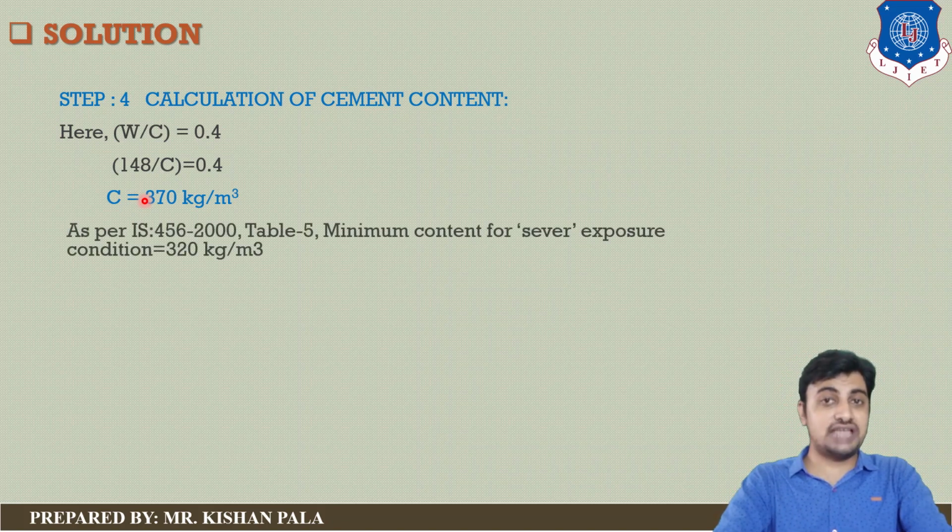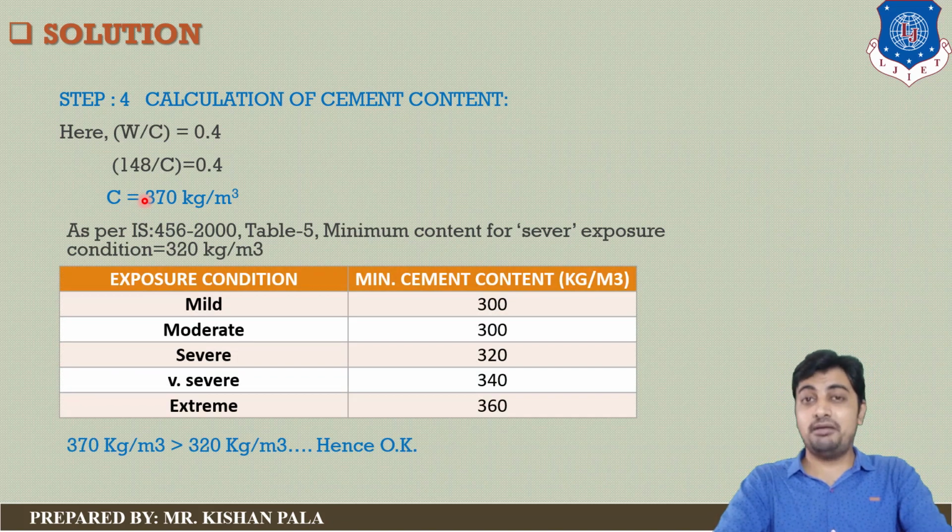But we have to check this value with the minimum criteria of Indian standard, and based on the data we have to take the severe condition, and based on the severe condition you require at least 320 kilogram per meter cube, but we have taken 370 kilogram per meter cube, so it's okay. Otherwise you have to take the greater of the two values.